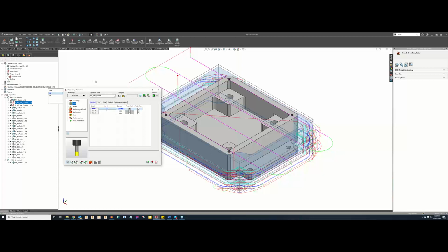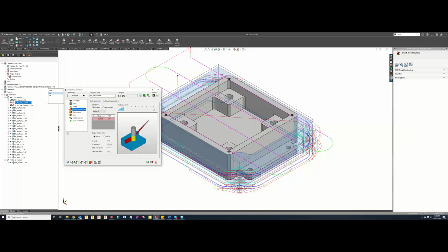Yep. Now, what I was getting at before is if I wanted to switch, so let's say my 20mm, I want to run as fast as I can go. So I can run level 8 on my 20mm, or my tool number 2, but maybe on my number 4 tool, I want to run at a level 5. That's how you can switch back and forth between these two, just by coming up here. There's no need to save and calculate and come down to number 4. Once you save and calculate, it will save and calculate both tool number 2 and number 4, and there is no reason to exit out of this operation and go into this operation down here. Everything is automatically adapted for that.